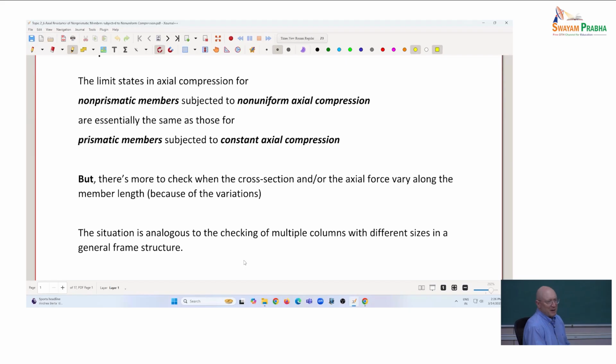If it's a non-prismatic member, think of each of the cross sections as a separate member. Generally, we would have to talk about how we can calculate gamma E, the elastic buckling eigenvalue. But if we have that, then I can get a stress at buckling at each of those cross sections. We'll treat each of those cross sections like a member and do the calculation.